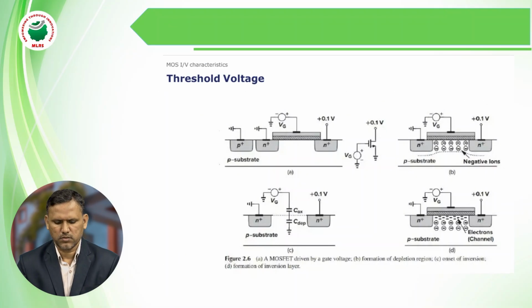Next, threshold voltage must be considered before deriving the IV characteristics of a MOS device. We have to consider the threshold voltage levels. Threshold voltage means that at a certain voltage the junction begins conduction between the source and the drain, as we increase the depletion width by applying supply to the gate. Based on the gate supply, the current flow from drain to source may vary with respect to the gate supply.